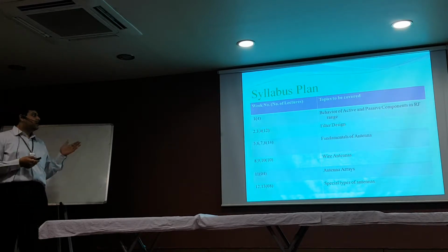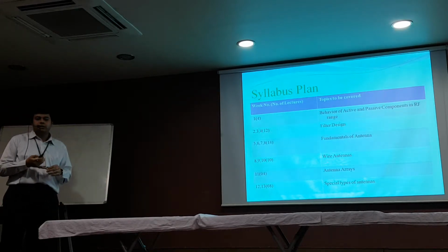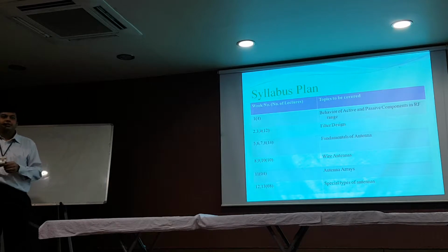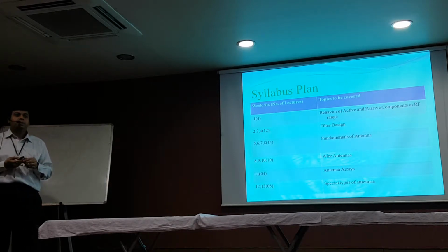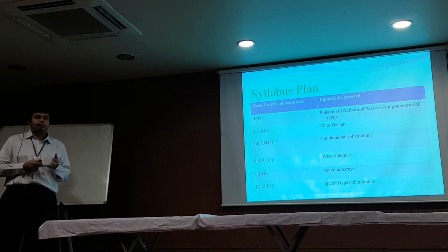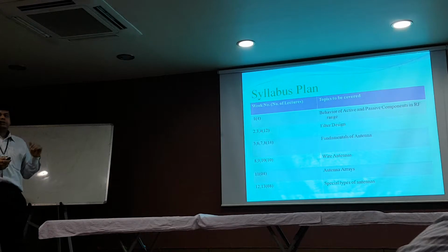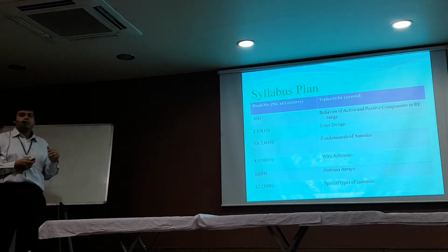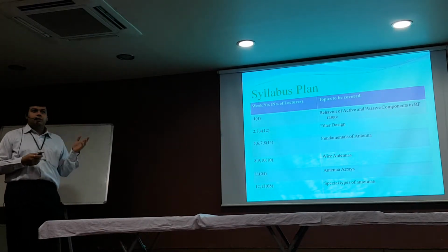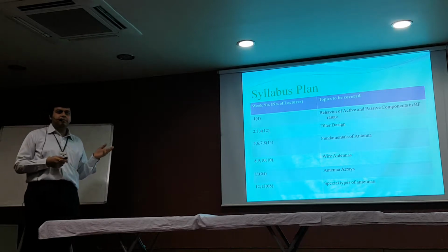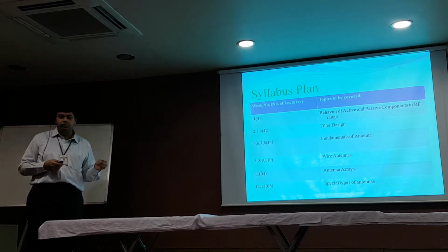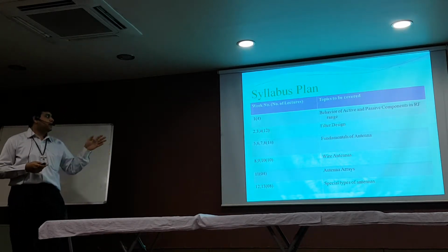So we are studying the different parameters of antennas, such as the gain, radiation resistance, directivity, beam width, beam solid angle, beam efficiency, and many more. Then the Friis transmission equation, which is required for transmission and reception, PR equal to PT GT GR, lambda upon 4 pi r the whole square. This will also be derived over here.